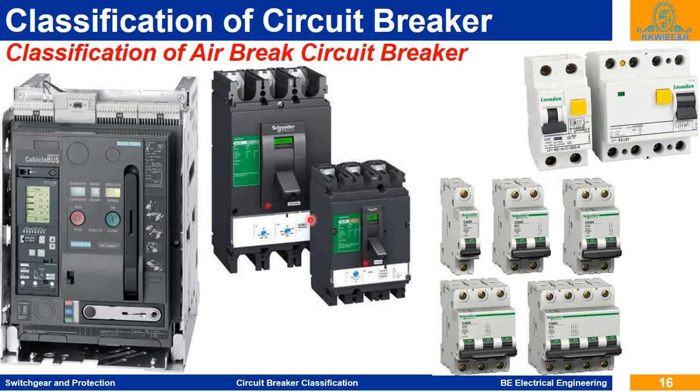Next is the MCCB, molded case circuit breaker. So this is a molded case circuit breaker, MCCB. In this MCCB, microprocessor based relays and thermal relays are available. Single pole, double pole, triple pole and 4-pole MCBs, miniature circuit breakers. And here you can see double pole and 4-pole RCCB or ELCB. So this is the classification of air brake circuit breakers which are used in low voltage.